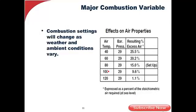Not at all uncommon, especially down south in the summertime. That temperature in the boiler room creeps to 100. You've got no control over that. Or it goes to 120. Look what happens to my margin of error. 9.6, 1.1. I'm getting close to stoichiometric here. Pretty dangerous. Now, if I go the other way, I'm blowing that nitrogen out the window, right? 78% of our air, where I go from 80 degrees to 60 degrees in that boiler room here in Milwaukee. The air is now denser, it's colder, it's denser, and as a result, my excess air increases. I'm just heating that air and blowing it out the stack.